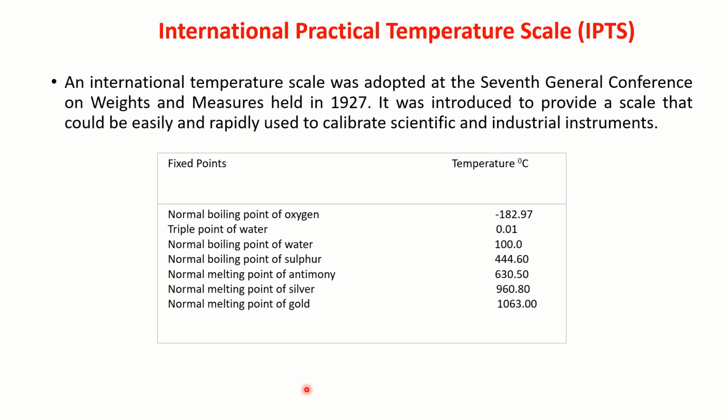So how exactly do we relate this new value of pressure to determine the temperature? I must have a scale, correct? And this scale should be standard, accepted by all. So for that reason, we need to calibrate these kinds of thermometers. For calibration, we require certain standard points.